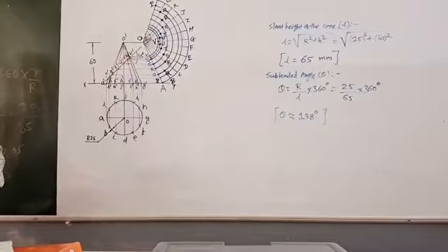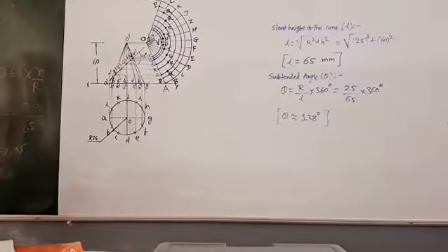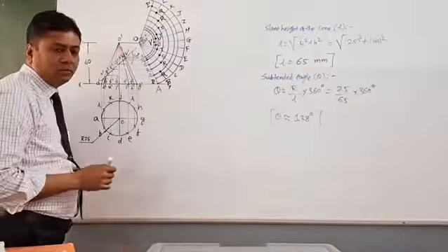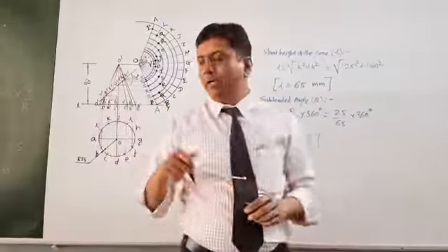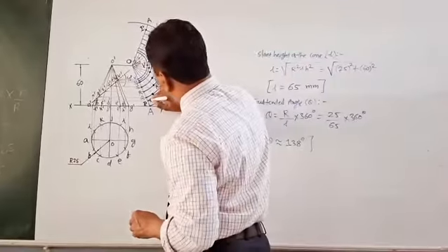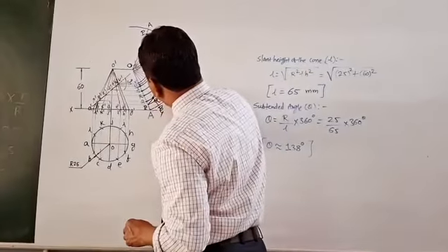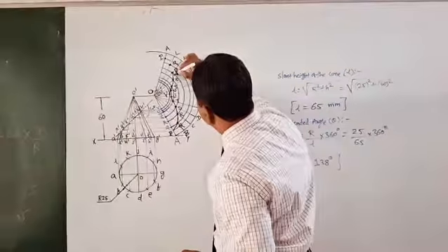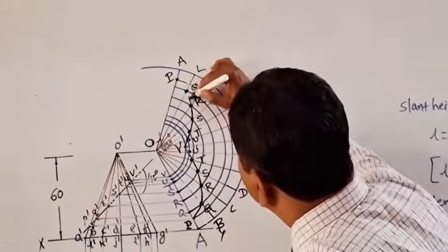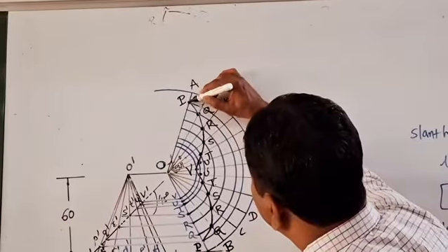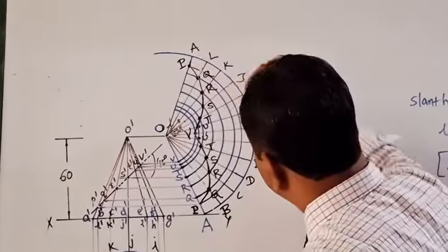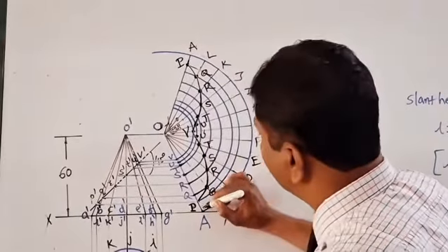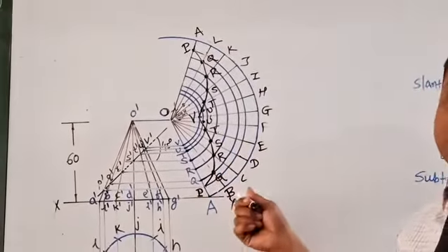So I got all the intersection points. With the help of French curve, starting from P, draw a smooth curve. Now where you draw it? This will pass through P to R. Yes. So you have to make it dark. This is straight.